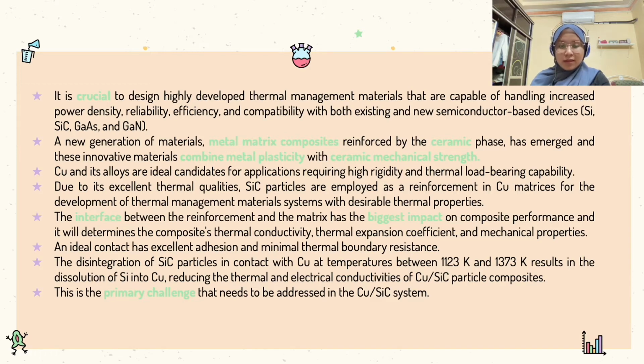So the contact interface between the reinforcement and the matrix has the biggest impact on composite performance. This contact will determine the composite thermal conductivity, thermal expansion coefficient, and mechanical properties. So, an ideal contact should have excellent adhesion and minimal thermal boundary resistance.